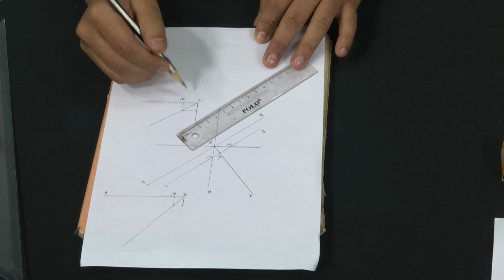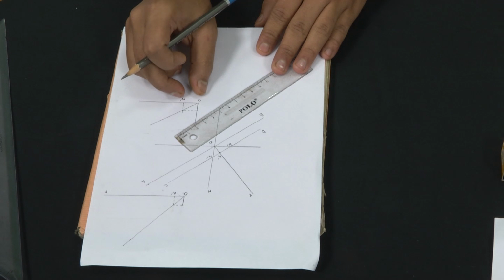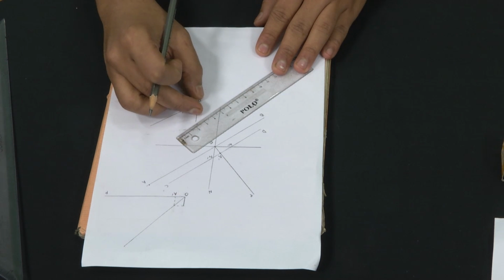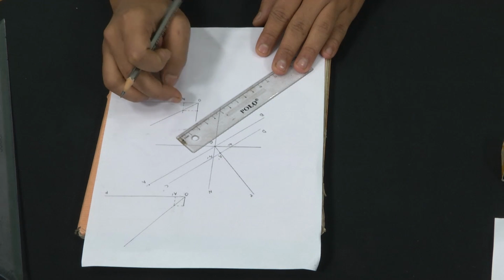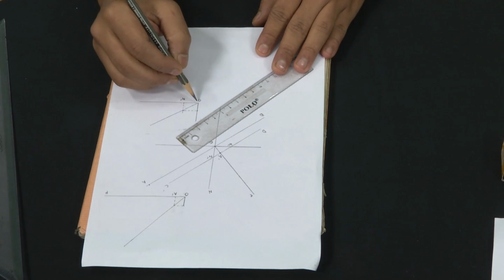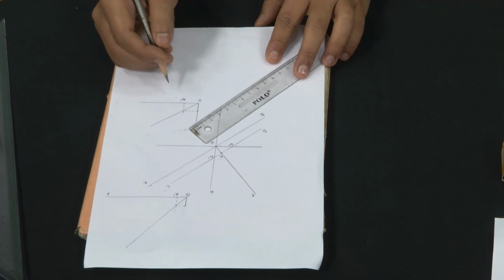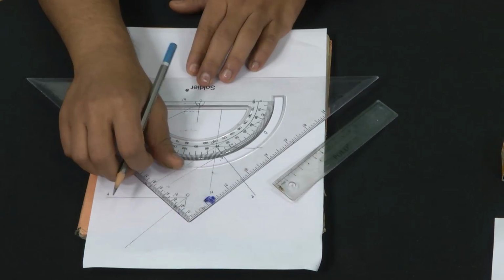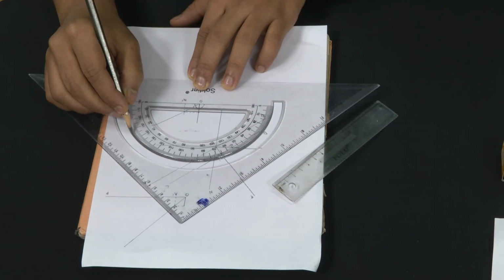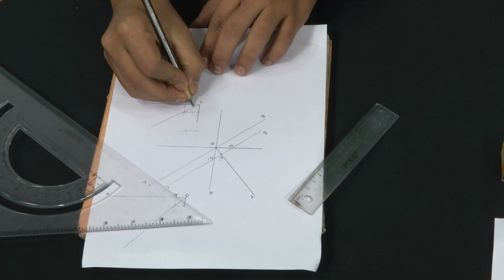lineation contained in this constant bed and trending due north, because this is our plane separation and this is our vertical separation. So, when we project the plane and vertical separation and come to a point where the horizontal and the vertical separation meet, when we join that point with the origin, the angle it makes will clearly be the plunge. So, this is our plunge angle trending due north, and I measure it with a protractor, and the angle comes out to be around 36 degrees.